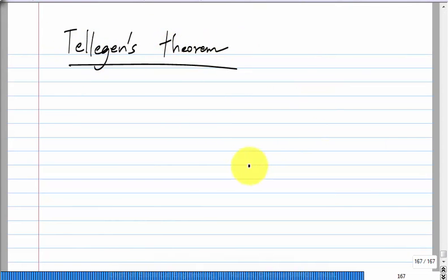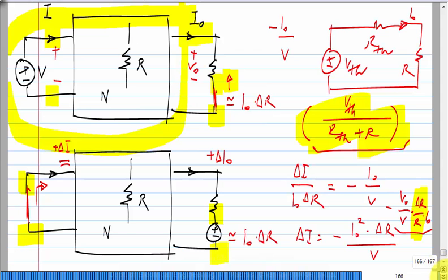It says that if you have two graphs, I mean, if you have a graph, right, and the circuits can be anything. You have two circuits with the same graph, then the sum of Vk Ik hat is 0, where V is taken from one circuit and I is taken from the other circuit. Okay, this looks vaguely like the conservation of energy, although V is from this circuit and I is from the other circuit. Okay, this is just a consequence of KVL and KCL. So I don't know what to make of the statement that this comes out of conservation of energy. Probably everything comes out of that. So I have to think about it a little more.